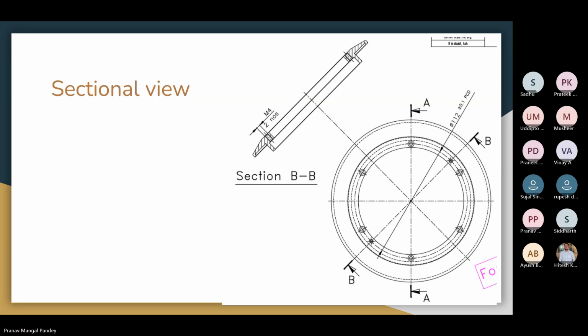So to uncover those details, what we sometimes do is, instead of putting a top view or a left view or a front view, we add a sectional view and then define the section. For example, the section view is B to B section, and then this is defined on the other views.